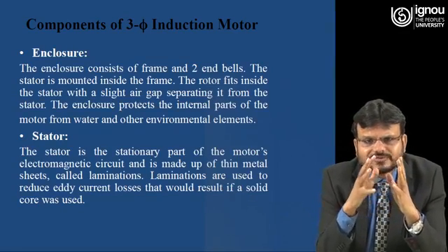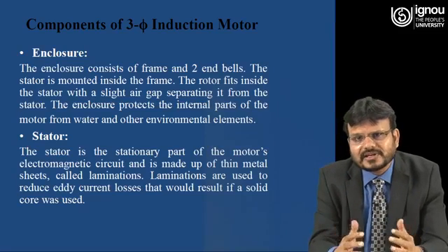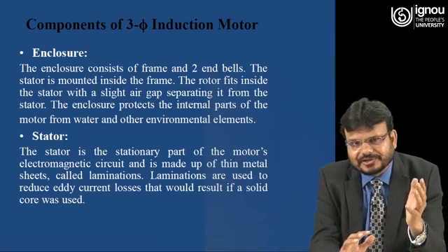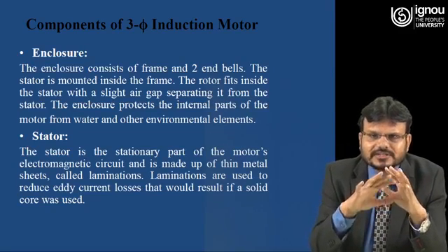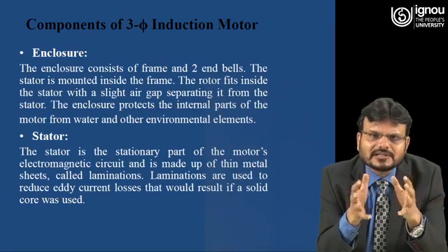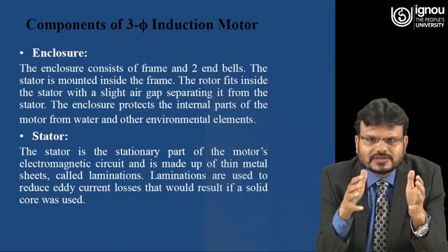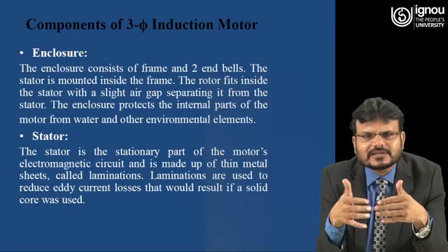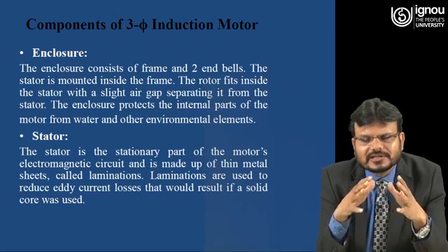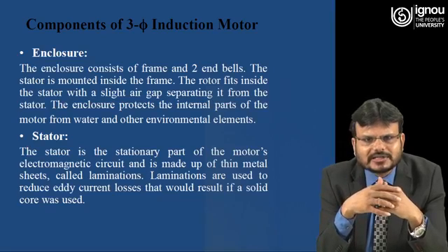So what is the function of this enclosure or frame? The enclosure consists of a frame and two end bells. The stator is mounted inside the frame. So basically you can say the enclosure is just like a house. In the house there is stator and rotor. The rotor fits inside the stator with a slight air gap separating it from the stator. The enclosure protects the internal parts of the motor from water and other environmental elements.